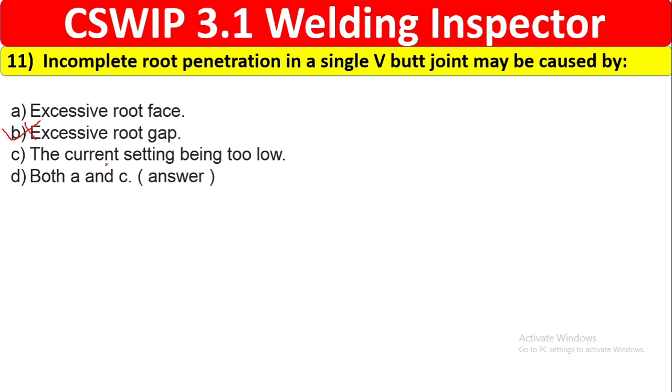The current setting being too low. Maybe. With an excessive root face, root penetration will not be there. If the current is low, there can also be not enough root penetration. So the correct answer will be both A and C.